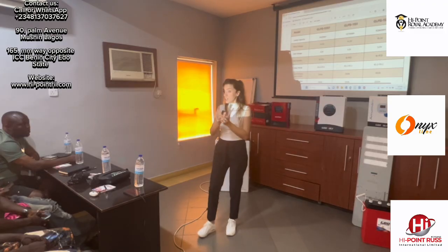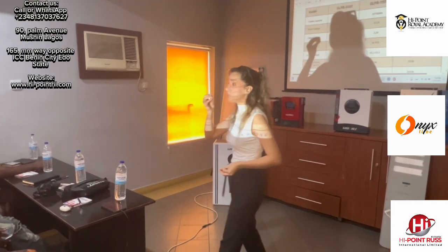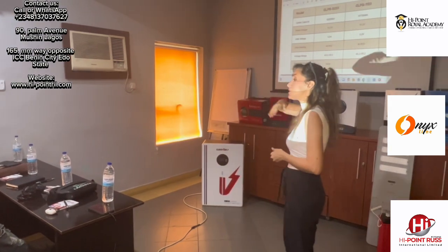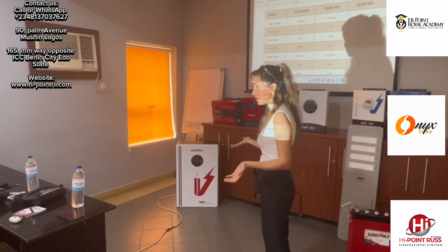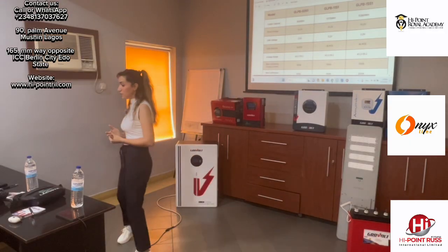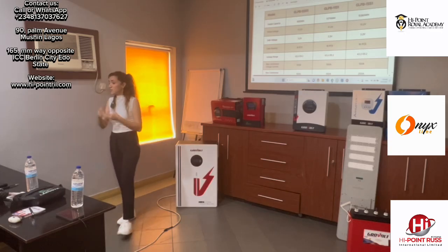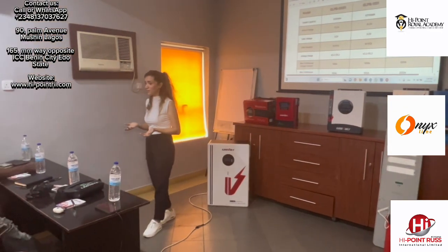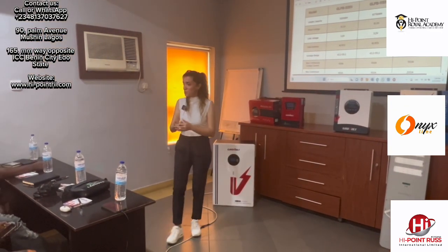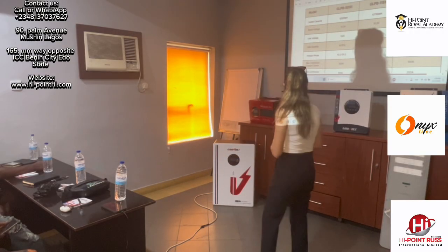So it doesn't reach 15 kilowatt at all. In general, if your battery is 15 kilo, you can't use the full 15 kilo, right? Because of the DOD and the discharge current. So if your battery in fact is not 15, maybe you will not reach 12. Okay, this is about the lithium battery.